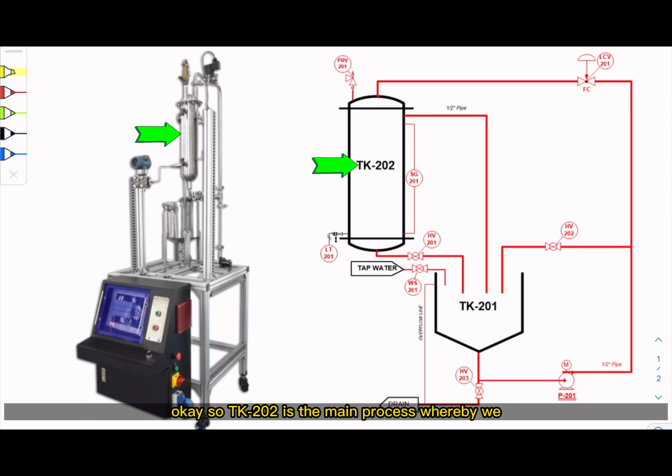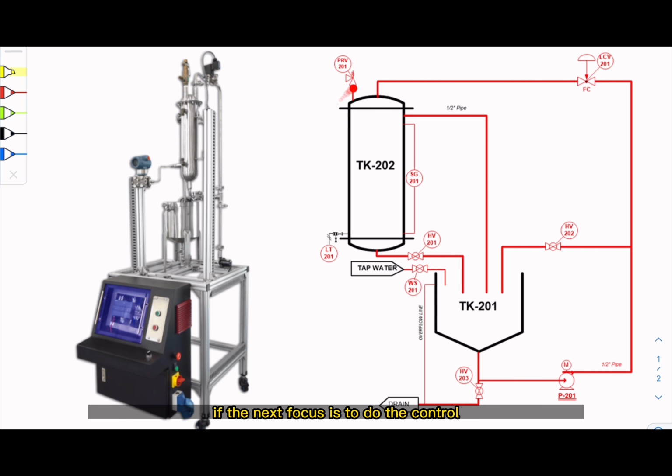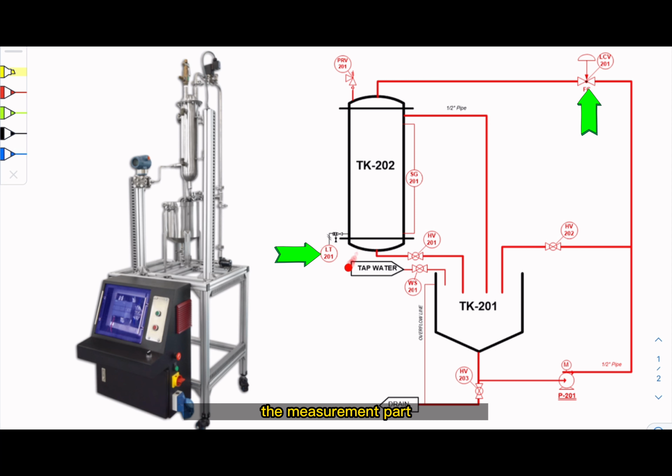TK202 is the main process, whereby if the next focus is to do the control, we're going to create the control loop between the level transmitter and the level control valve, whereby the level transmitter is the feedback, the measurement part, and this level control valve is the output.